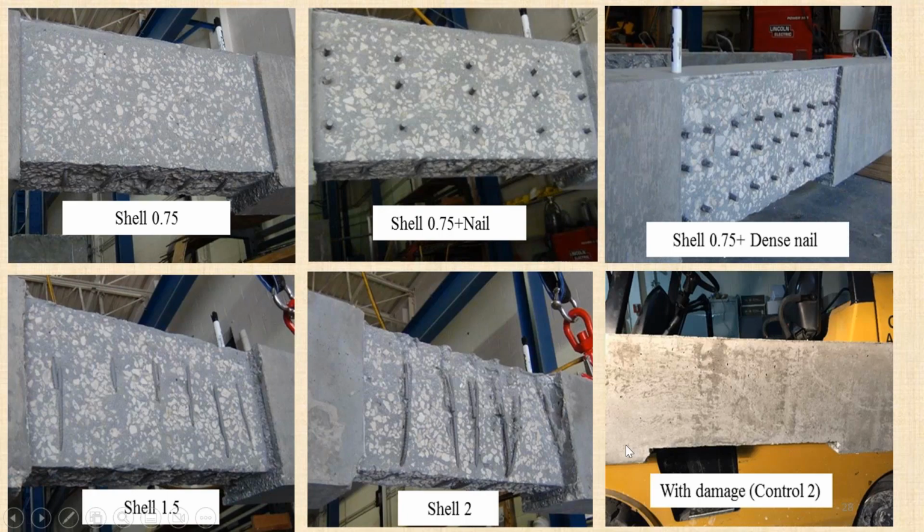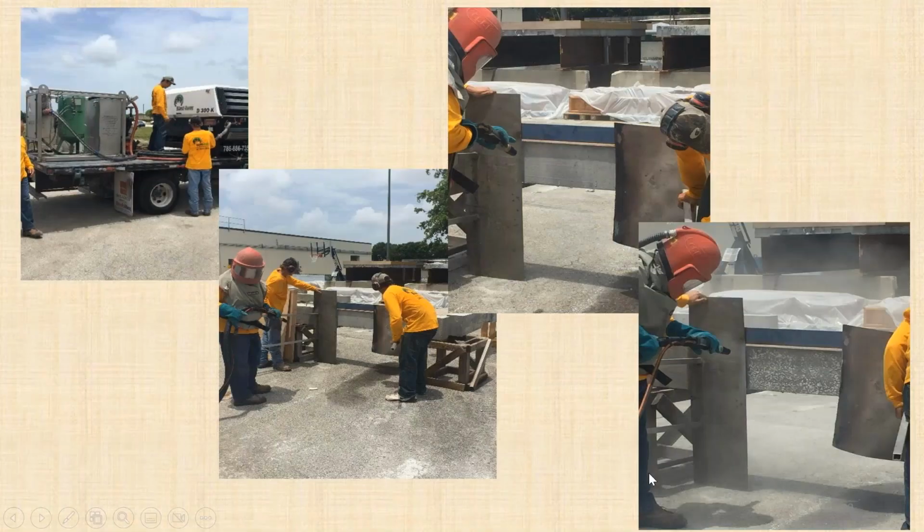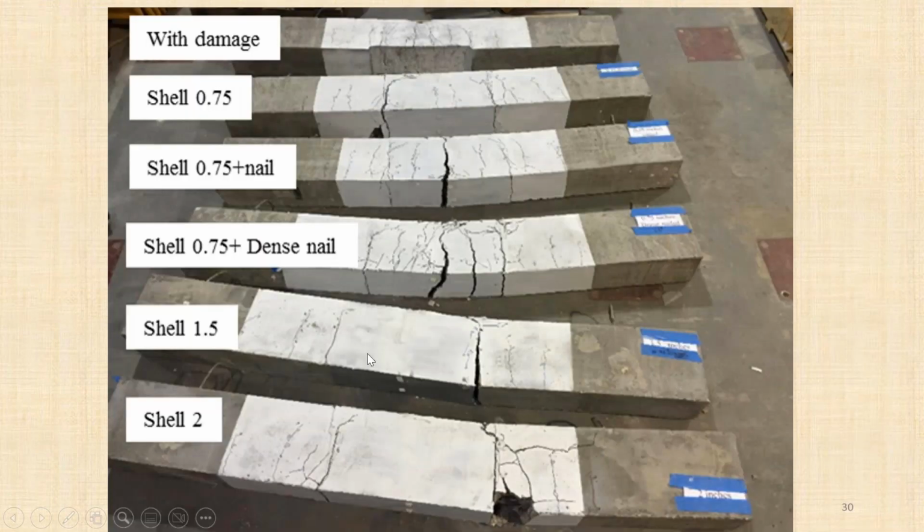I can tell you this. This is a very major lesson. Of course, we always use sandblasting and prepare the surface. Anywhere you put UHPC, you really force the damage to be outside that, unless you put a very thin layer. But if you put any, let's say 1.5 inch in these beams, 1 inch, 0.75, or even 1.5 inch, the damage is going to move away from it.